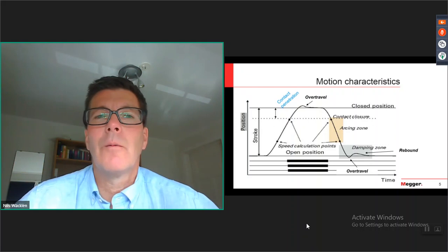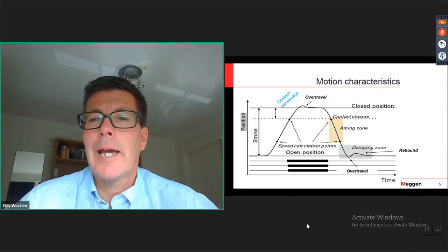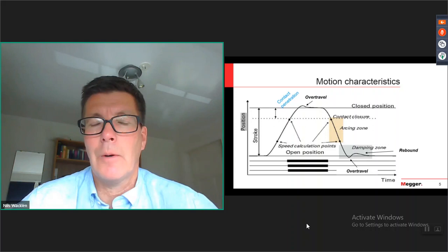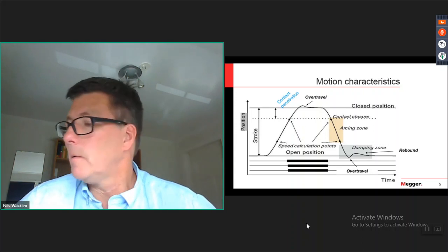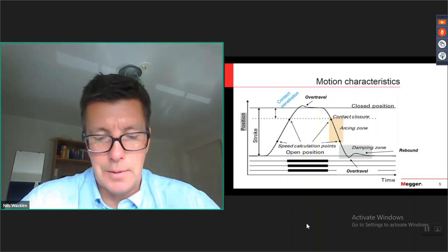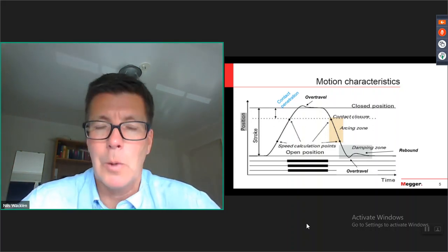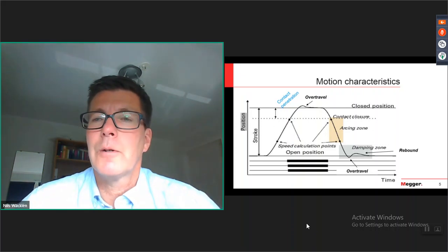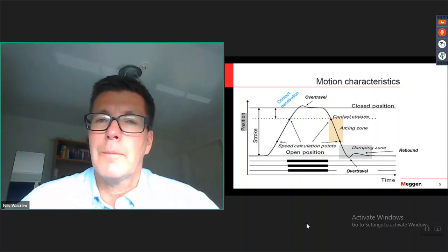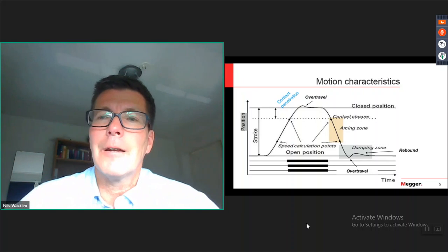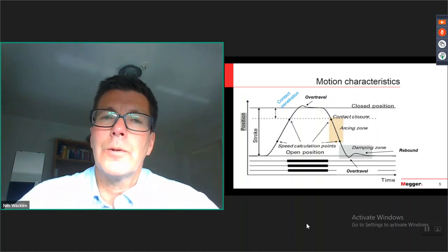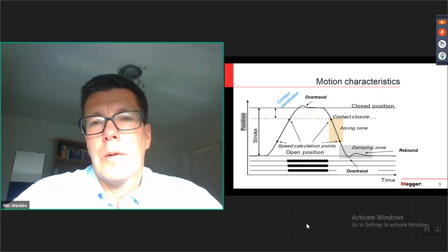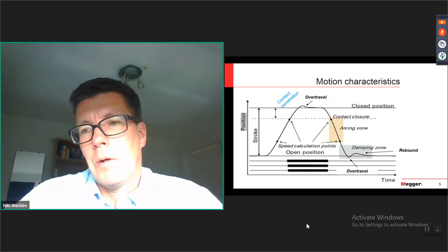It's more that when you open the breaker, it should carry the arc and stand the heat of the arc. But this can cause contact bounces at the closing. You can see perhaps first touch, but then it's bouncing a little bit until the main contact goes in. And after that, there shouldn't be any bounce.